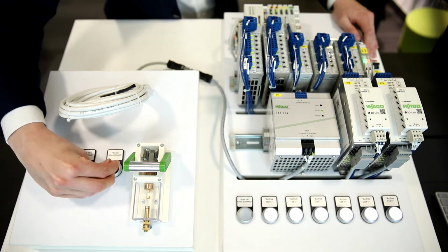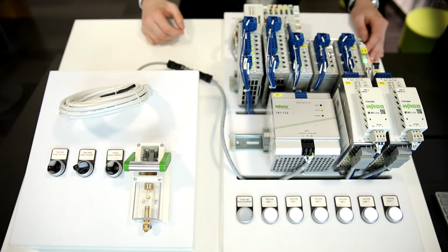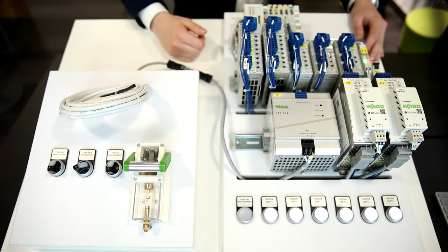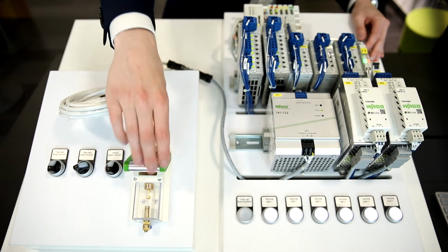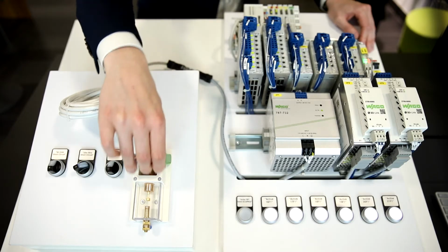Now we will choose the 20 meter wire. So right now we have a short circuit after 20 meters. This is with the high resistance of the wire. If we now produce a short circuit, we have more than double the nominal current, which our miniature circuit breaker can handle. So it has a great time lapse for its trigger.